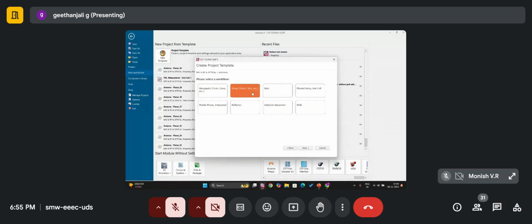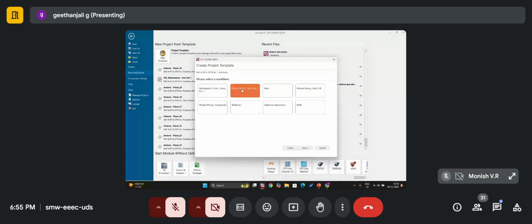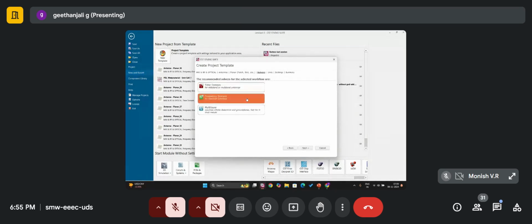Planar patch and slot. As Sir said from yesterday's session, the patch is used to design the band stop FSS, which we have designed now, and the slot is used to design the band pass FSS. So for that band pass FSS, we have to etch the resonator. I will show you now.